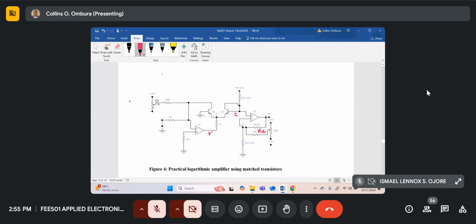Most of the op-amps, as I said, if you ground the two inputs, you'll find there'll still be some output voltage due to the offset voltages that appear at the output of the op-amp. So this is the circuit that you should be able to do in the lab.